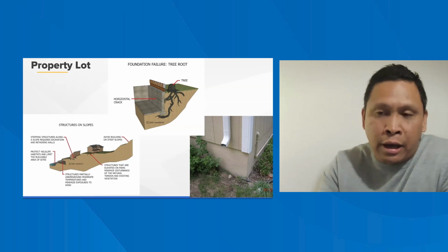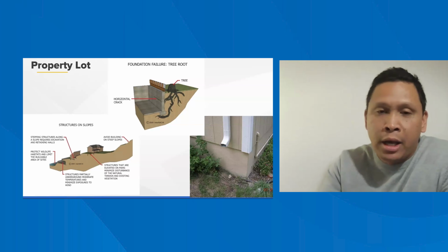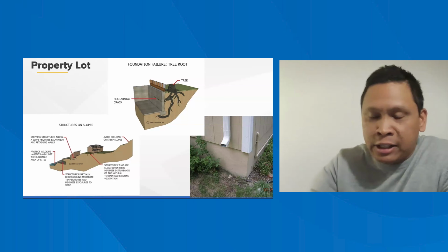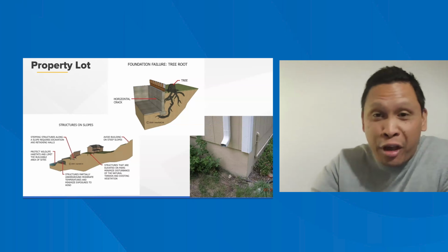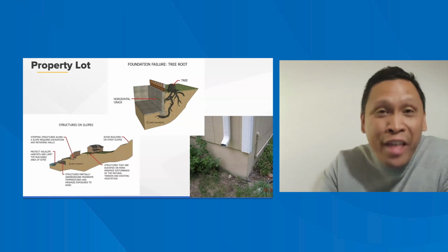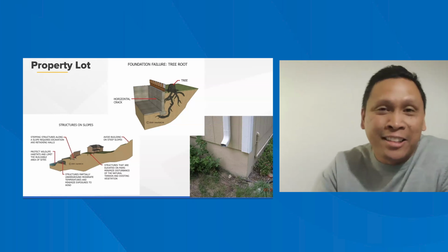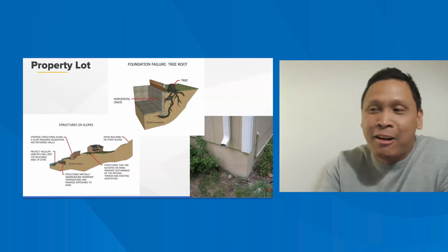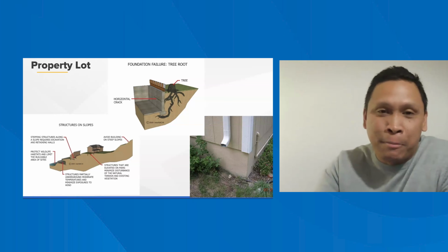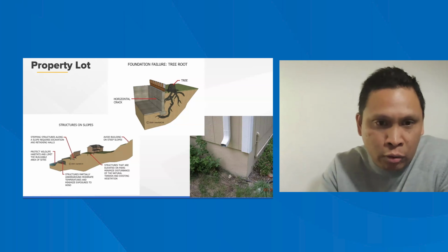And oftentimes, I think we've all at some point come across homeowners who are mulching the exterior of their home, and they've got a really nice thick mulch bed, right? But it's so thick that it's coming in contact with the bottom part of the wood siding or the sill plate, and we need to remind them, hey, we need to make sure we're keeping all of this moisture away.